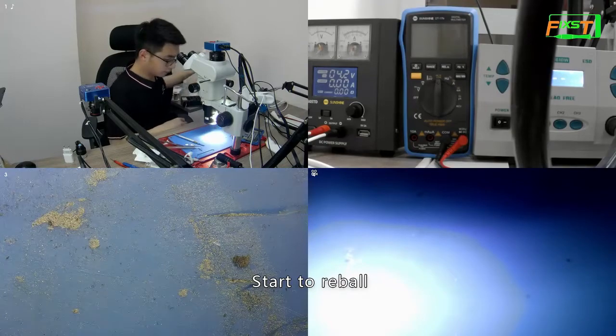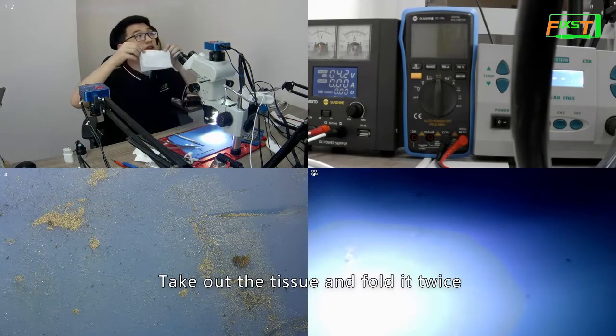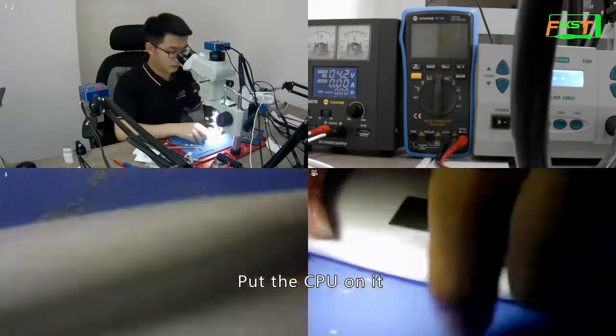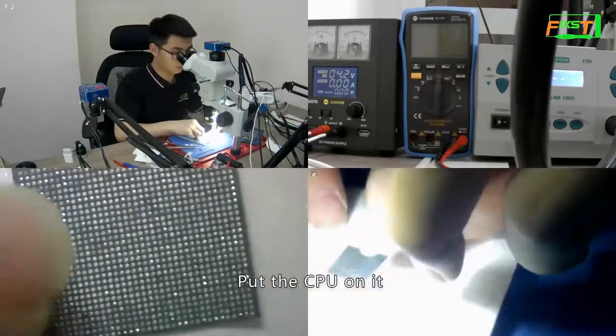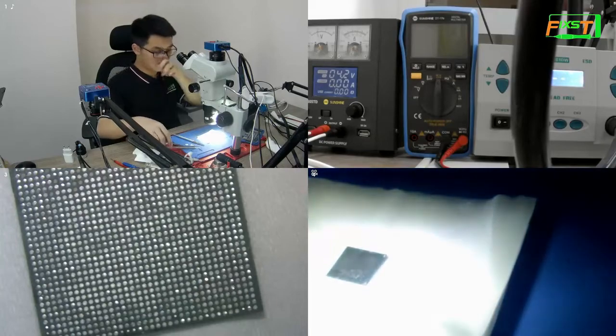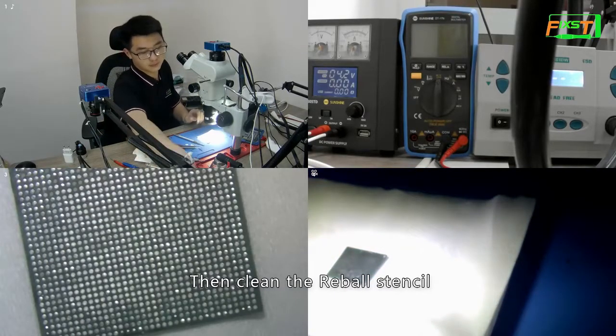Start to reball. Take out the tissue and fold it twice. Put the CPU on it. Then clean the reball stencil.